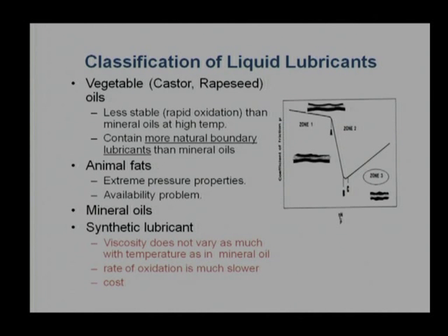The major advantage which is generally quoted is the viscosity. Viscosity degradation is very, very low. Viscosity index is generally higher than the viscosity index of mineral oils. Few synthetic lubricants are slightly costlier compared to mineral oil and can be utilized for common applications. Otherwise, by and large, synthetic lubricants are costlier, even 3 to 4 times compared to mineral oil. That is why they have restricted applications and are used when we do not have any other alternative.